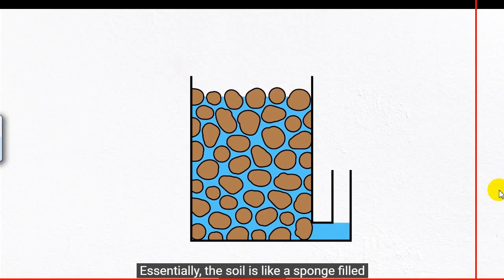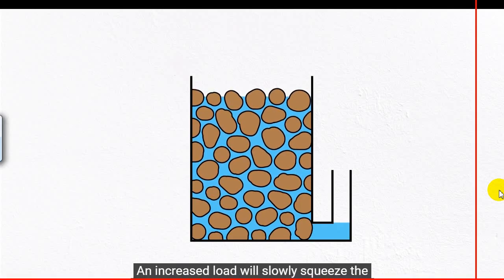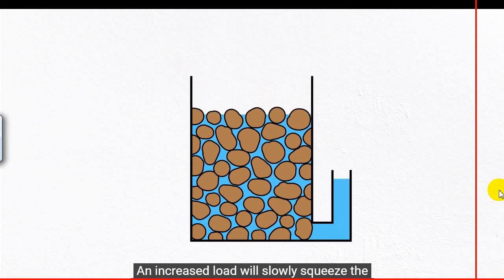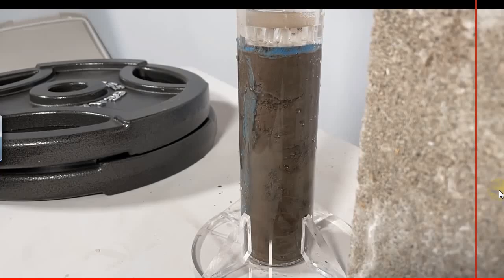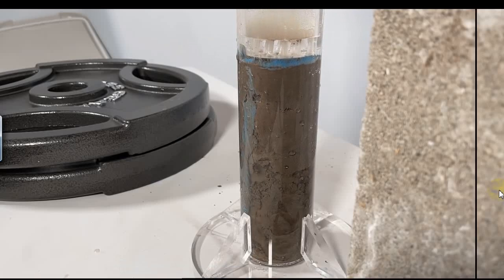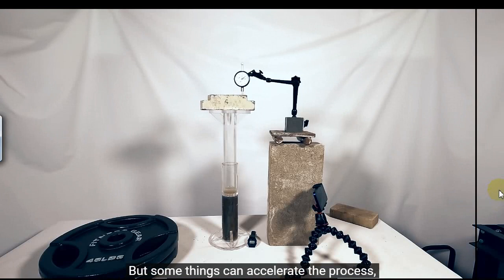Essentially, the soil is like a sponge filled with water. An increased load will slowly squeeze the water out, allowing the grains to compress into the empty space. Settlement is usually a gradual process because it takes time for the water to find a path out from the soil matrix. But some things can accelerate the process, even if they're not intentional.